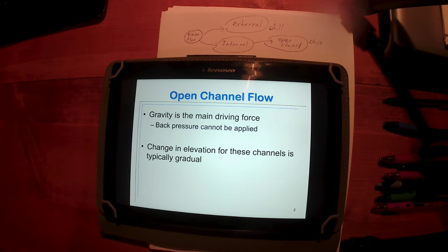And here's the thing: if I'm moving water, I don't want that water to pick up a whole lot of speed. I don't want it to have a lot of kinetic energy. Water with a lot of kinetic energy is very destructive. It's very hard to control. It tends to erode or chew up whatever we flow it through, especially if it's picked up any gravel or anything like that, as most open channels do. So the more speed it has, the less time our designs will survive in a high-speed flow scenario.